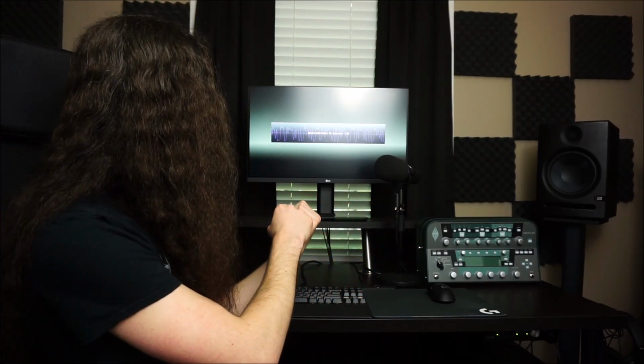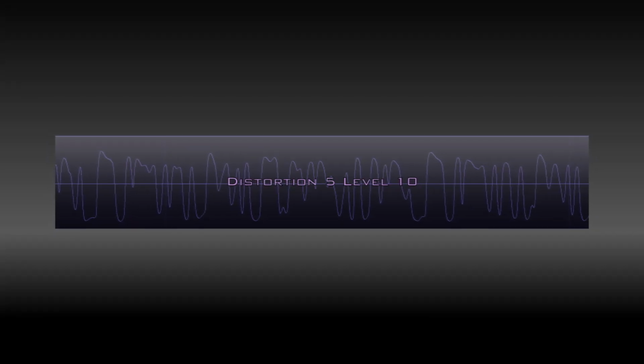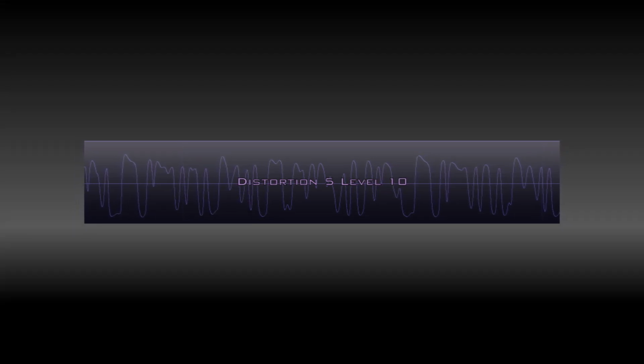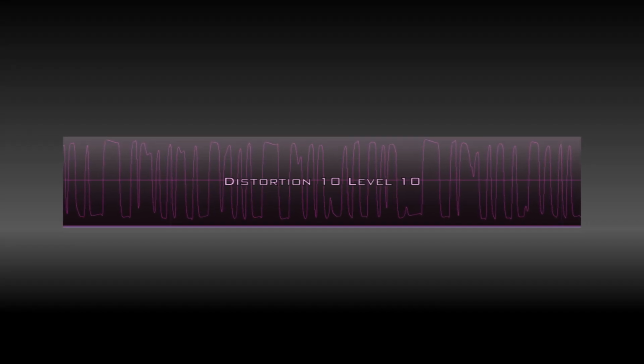And distortion and compression, when you start mixing the two, things get really complicated, but really, really interesting. So coming back to our amplifier and our pedal situation here, you might have already picked up on this, but as you can see, as the distortion level is turned up on this pedal, not only does it gain a more hard clipping profile, but the differences between the lowest amplitude peaks and the highest amplitude peaks start to decrease. So by adding distortion to the signal, by spending more time near the threshold, we've actually decreased the dynamic range of this signal at the same time, even though we didn't even really mean to.